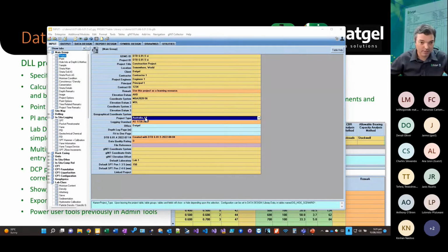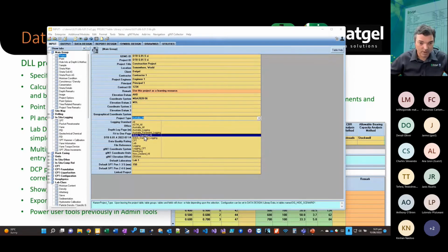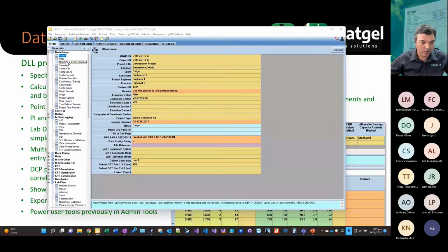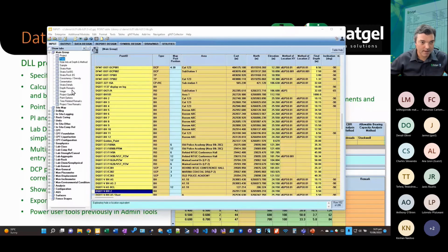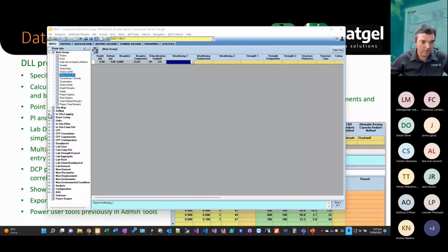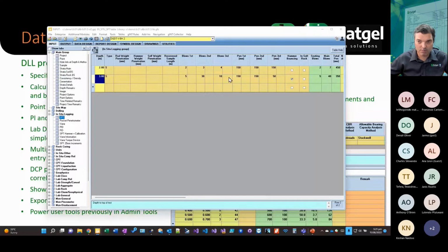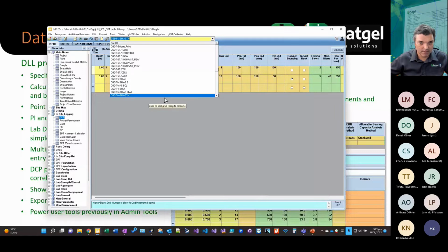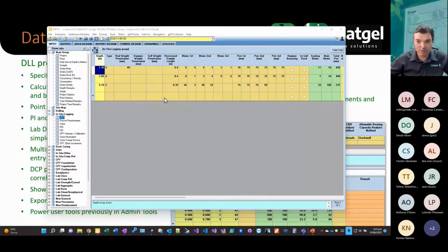So we can customize the interface to show different standards. I think for this audience we have now, the British standard interface would be the best one. So now we can see the British standard strata description tables. Should be able to see the 6 blow counts here. Enter those in here. And if I go to the British standard example borehole, it might be a bit more practical. So we can show and hide the fields, show and hide tables and groups to customize the interface.